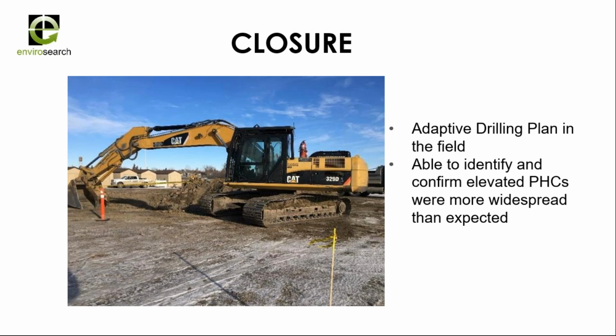And I guess the other note, from both of these studies, to summarize, is that when you're talking about diesel or those heavier end contaminants, and particularly when it's colder conditions, we got very poor results from the PID as a screening tool. And the other comment I want to make is that even though we did allow the samples to warm up and give them time for the hydrocarbons to volatilize into the head space, that also is a huge time sink when you're collecting samples in the winter.